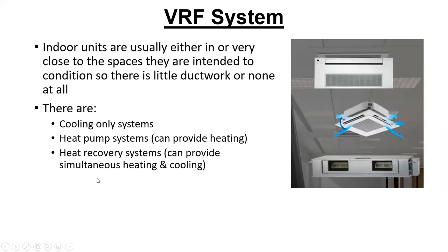So that's something to note for sure. There are cooling only systems, probably not in this part of the country, but there are parts of the world that are so warm that they just don't have to worry about heating. Heat pump systems can provide heating and/or cooling, and heat recovery systems can provide simultaneous heating and cooling on the same outdoor unit. So you could have 6 indoor units and have 3 of them heating and 3 of them cooling. But see, these are all slight variations in types of VRF systems.